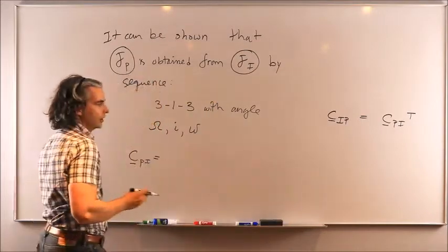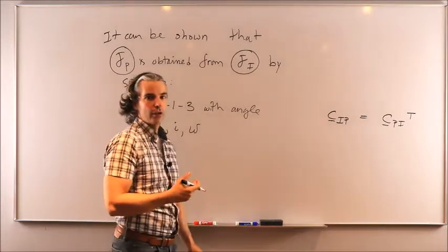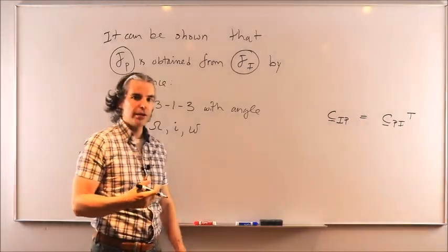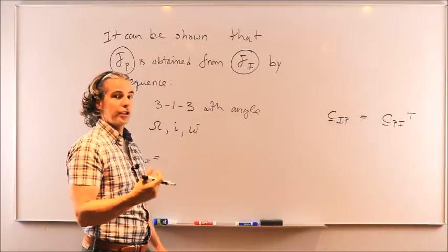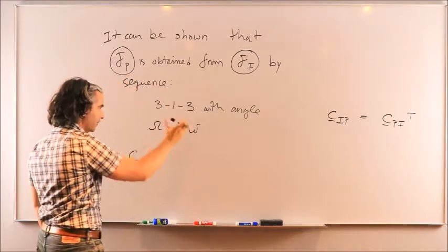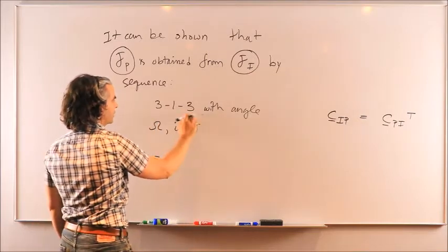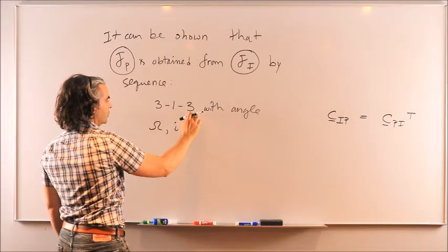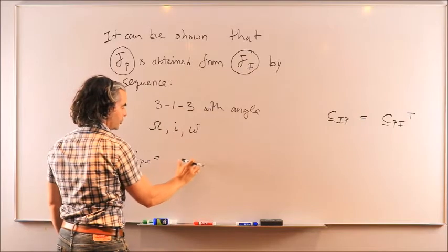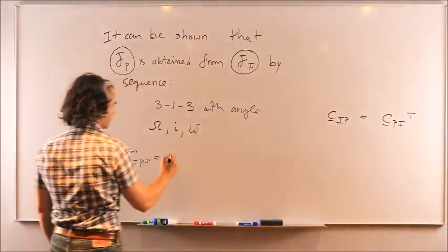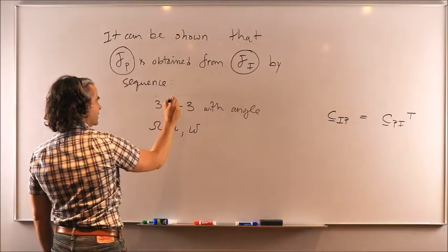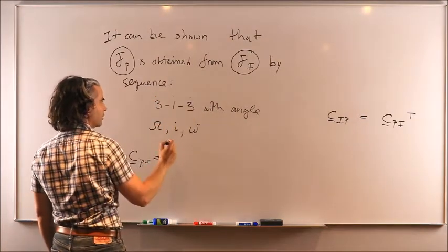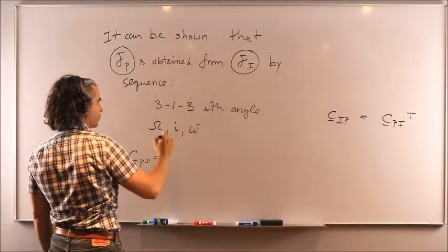And we had actually showed it on the board through the 3-2-1 rotation sequence, and you've been able to appreciate the fact that we do indeed need to flip the physical rotation sequence to get the order with which you multiply the principal rotations, okay? So this is the first physical rotation, second rotation, and third rotation. So I'm going to flip the order backward and write